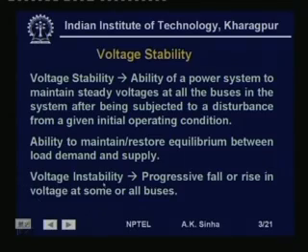So, this is how we see voltage instability, that is, when we are not able to match the system load demand with the supply, and when we talk about matching the system load demand, we are talking about both real and reactive power demand.